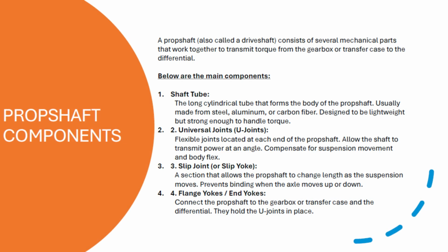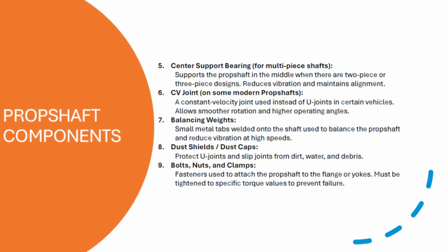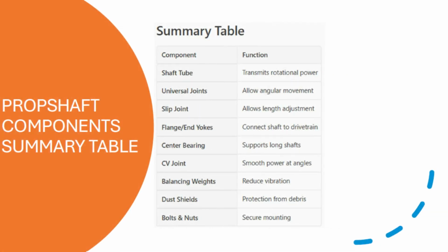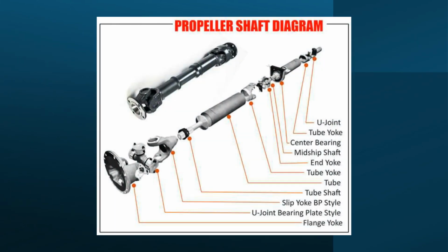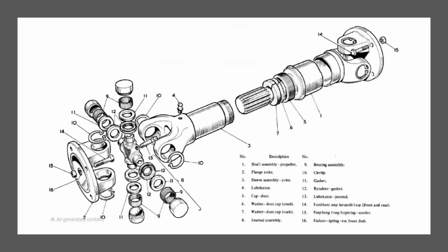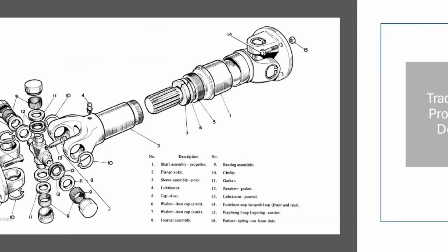This final section includes a series of assessment questions to test your knowledge of the materials covered in this video. Question 1. What is the primary function of a constant velocity joint in an automotive drivetrain? Question 2. Which type of CV joint is typically used in the inboard position to allow for plunging motion? Question 3. What is the most common symptom of a failing outer CV joint when the vehicle is turning? Question 4. Why is it critical to inspect the CV boots regularly for cracks or grease leakage?